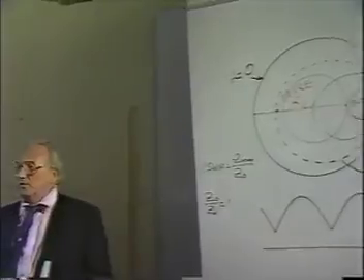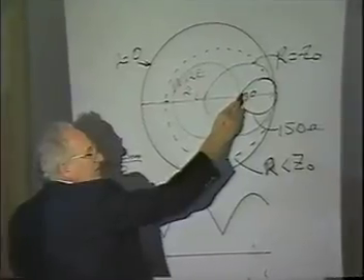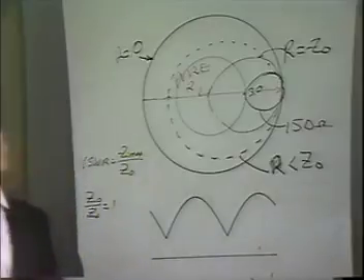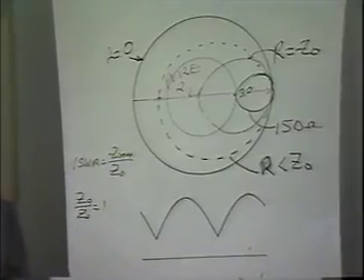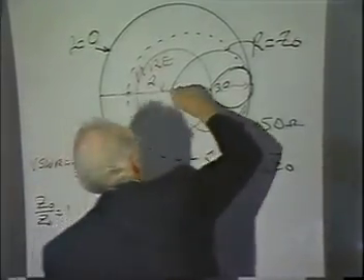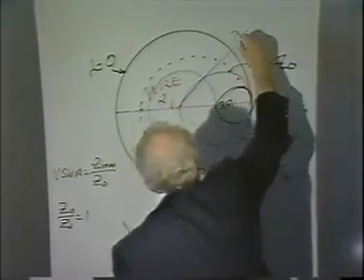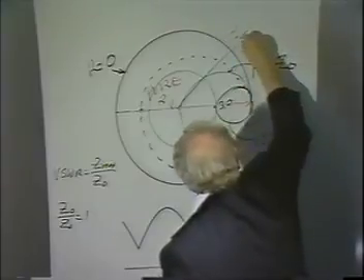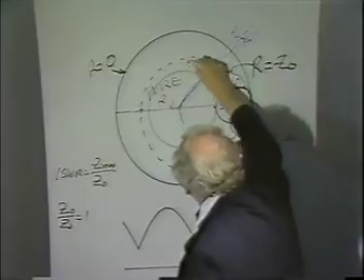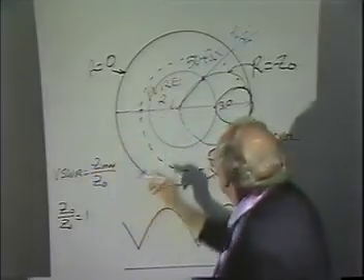Now something very interesting on this transmission line. We know that in this case, this is 150 ohms right here, right? We know that over here was 17.5 ohms. Someplace in between, what are you going to have? Some fractional wavelength over here, L over lambda, if you want to call it that. But notice this point here. What do you have here? 50 plus jX. What do you have over here?